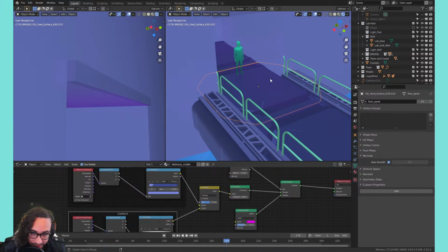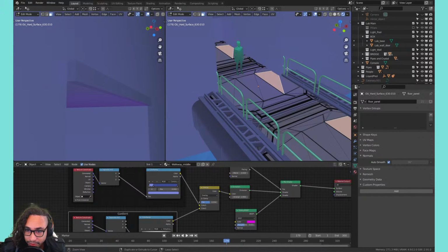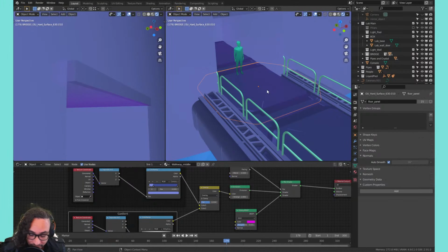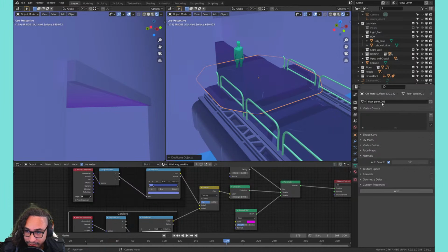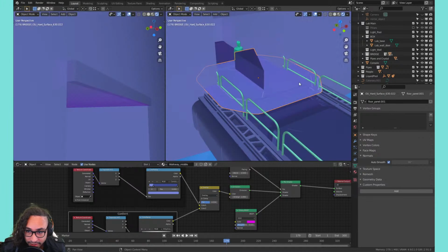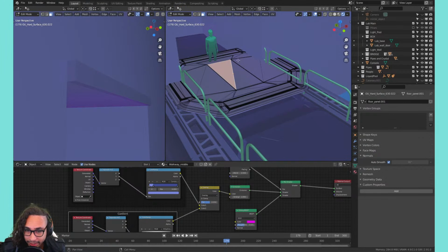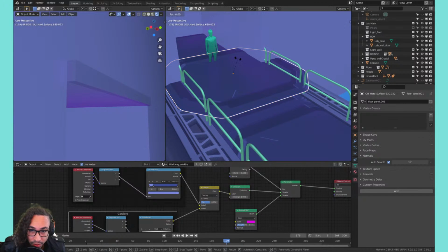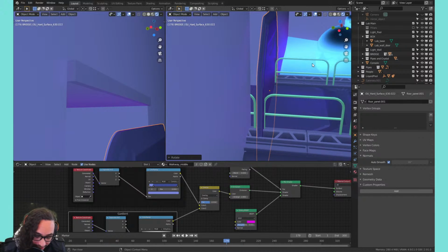So instead of doing that, I want to mess with the mesh for the door. So instead of hitting Alt D, which will make a duplicate with the same floor panel, I'm going to hit Shift D and see that floor panel. Let's do it again. See the floor panel here? It says floor panel, nothing, right? Shift D. Now it says floor panel .001. So this is a new mesh. So if I edit this, it's not affecting anything else in the scene. You see? My panels are still the same. And that's the difference between instancing something and duplicating something. It's very important to know so you can save space and stuff. So I duplicated it so I can mess with it afterwards.